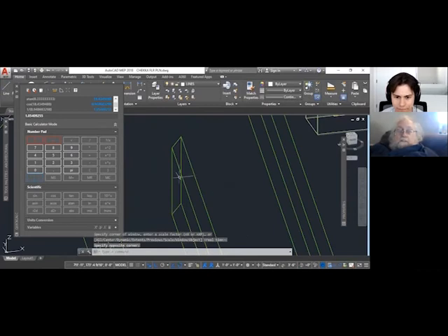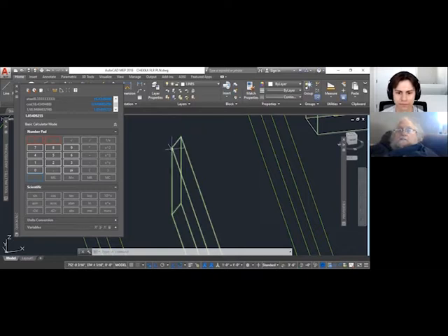You see how it's got a bevel to it? It's got an angle this way, and it's got an angle that way. This angle this way is done with your saw. You set your saw at a 45-degree angle. This angle this way is done with your framing square when you mark the line to cut it. And it's done at 18.43 degrees.